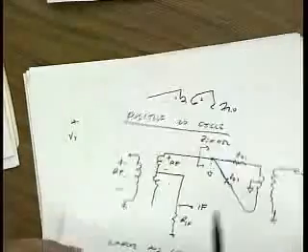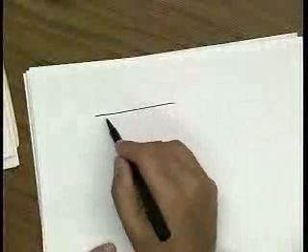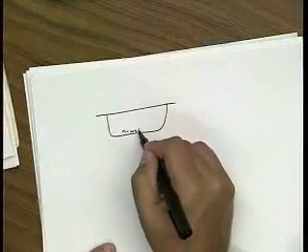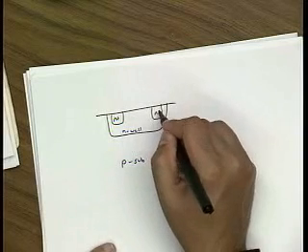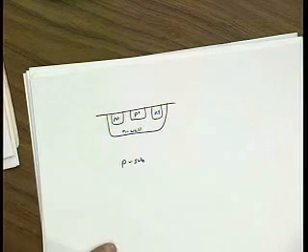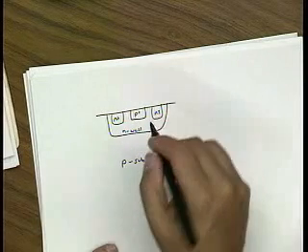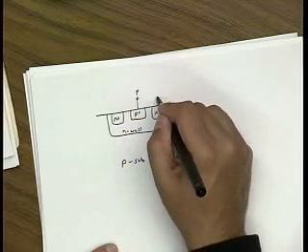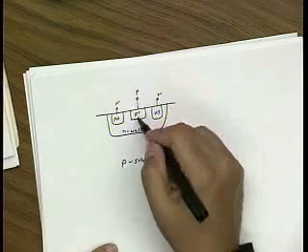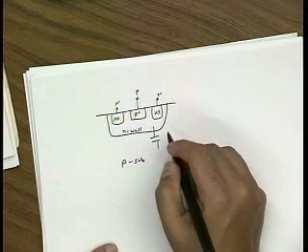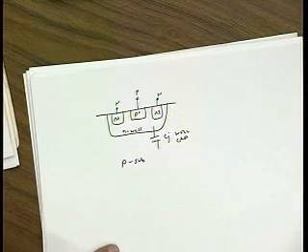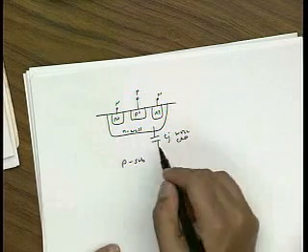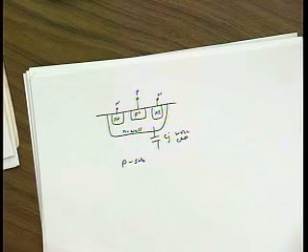So how would we actually build a diode? So the way we actually build a diode, maybe let's say this is an N well, this is a P substrate, and I'll have some N plus contacts, and let's say a P plus junction. So this is a PN junction here, and this is the P terminal, this is the N terminal. Well, you'll notice that the P terminal just sees a P plus, but the N terminal actually sees a well capacitance. So the physical way that you build it does have some asymmetry, but hopefully this is not playing an important role at these frequencies.